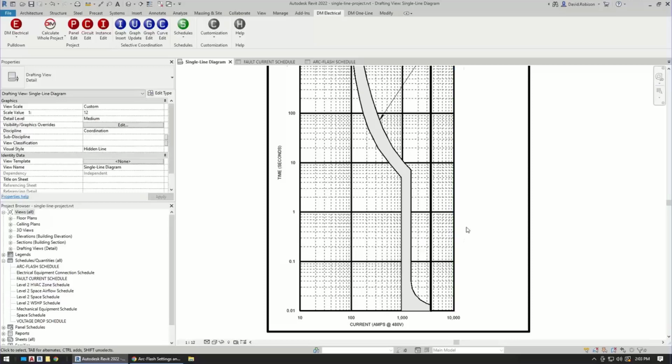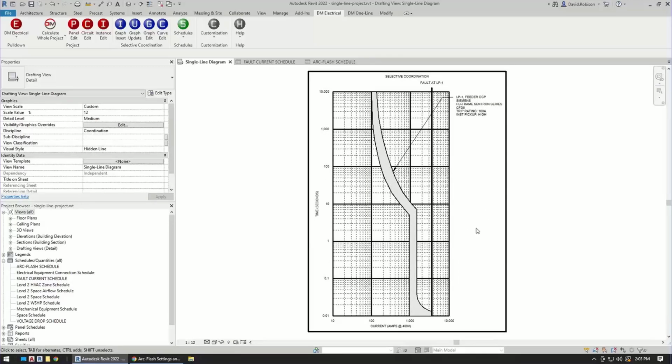The other is that in the 10 to 20 times the breaker rating is where this instantaneous curve ends up. So this is a 100 amp breaker, and it's 1,500 amps is where we've got this instantaneous value. So again, between 10 and 20 times is where you transition from 2 seconds to a single cycle. So that's where you could take a look at what that arcing current is and manually put in a value, not knowing anything about the breaker, just guessing that, okay, if it's more than 20 times, it's probably going to trip in a cycle. If it's less than 20, to less than 10 to 20, you're going to have to think about that a little bit. Less than 10, it's probably going to take 2 seconds to trip.